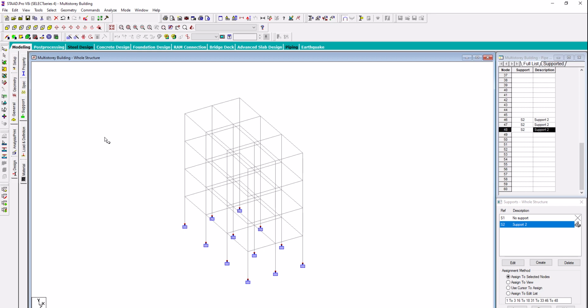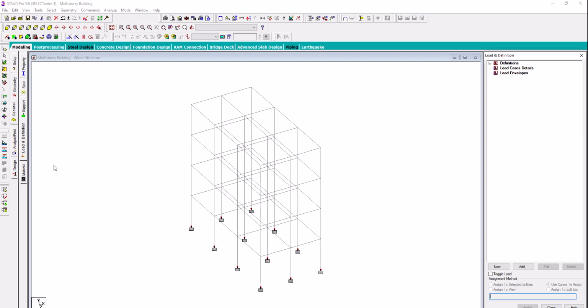Soon after this, I need to go for the calculation part. In this calculation part, I need to consider which kind of load is to be assigned first. As we have discussed, dead load is to be assigned, and then floor load, right, and then wall load, and then live loads, right.